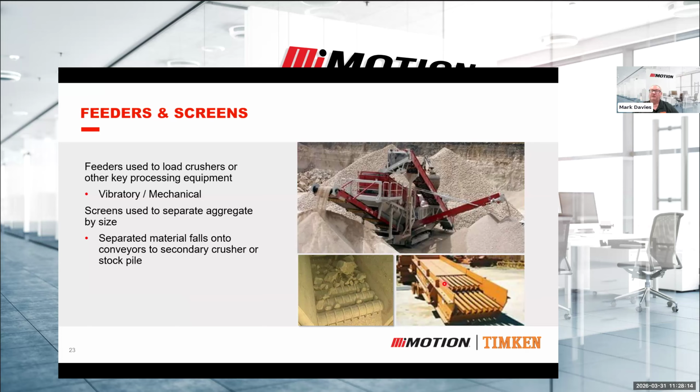So you'll see them every primary crusher will have a vibrating feeder that is feeding the rock, and it basically advances the rock into the crusher, into the throat of the crusher, and on every mine site you'll see a vibrating feeder of some sort. So that's exactly the same as far as the bearings go. It's the same type of bearings and the same specification of bearing as it is for the sorting screens.